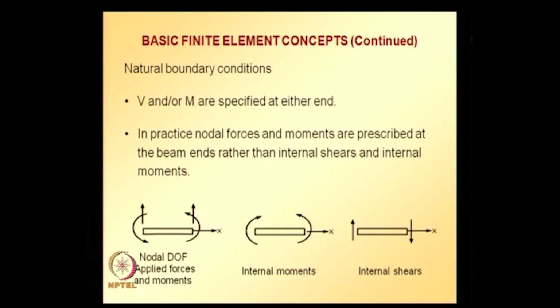So we should note down the relation between the nodal forces and moments and the internal shears and internal moments. If you go back and see the sign convention that we started out with, the first figure shows the sign convention for nodal degrees of freedom, that is, transverse displacements and rotations, and also the sign convention for applied forces and moments, whereas the second figure shows internal moments and the third figure shows internal shear.